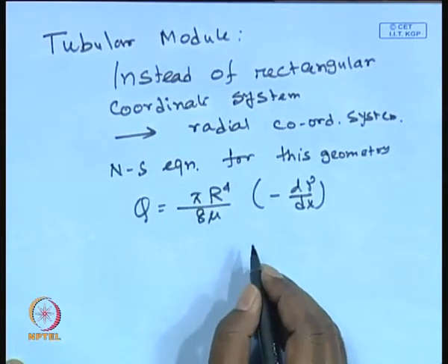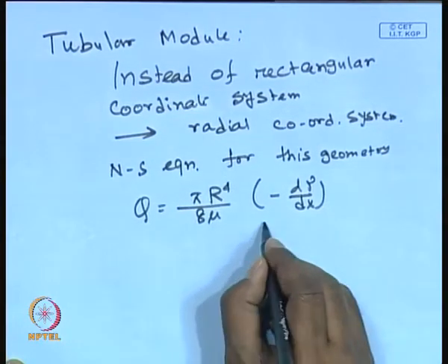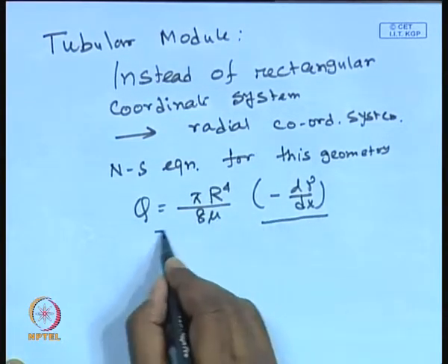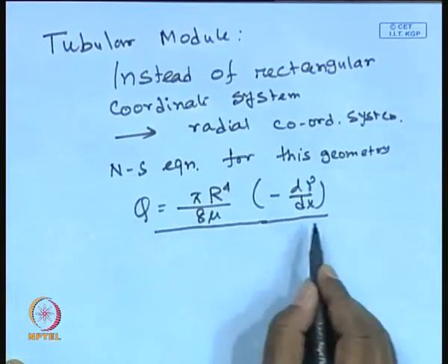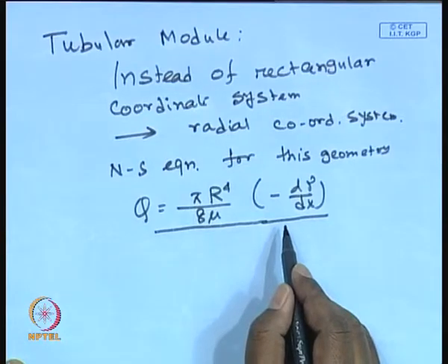Here we will make an assumption, and again I will emphasize that you should know the limitation of this equation. This equation is derived for an impermeable wall, but in our case the wall is really permeable. It doesn't matter, because the velocity in the axial direction will be in the order of meter per second, and the velocity in the normal or permeable direction will be in the order of 10 to the minus 5 or 10 to the minus 6 meter per second. So that really doesn't affect much.